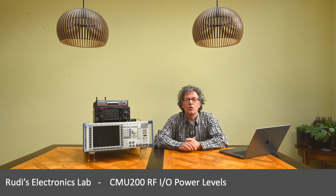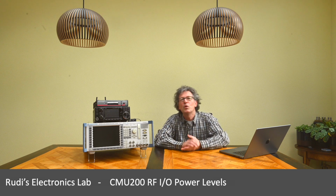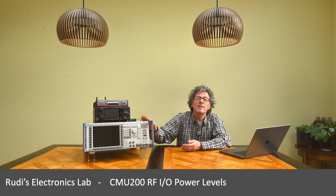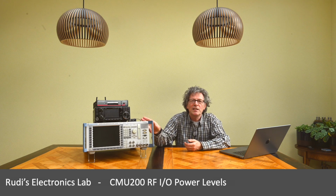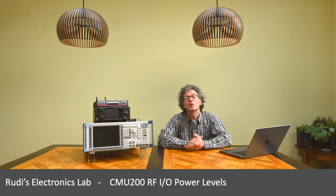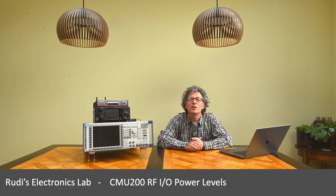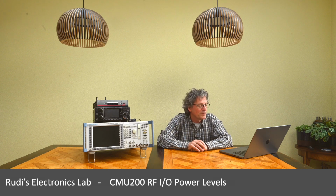You would normally have at minimum 2 different channels installed there, 2 different transmitters, with one of them having this BCCH channel, and the other one could be full of traffic slots. So you can mimic this basically in this way. And also in other standards, it might be important to have another type of carrier. There might be a pilot signal or whatever going on. So I think you really have to see the availability and the features of this in the light of what it was originally designed for. But we can use it for generic purposes, and I've used it for a couple of things. I hope this gives you some idea why we have this kind of unusual configuration of such a weak signal generator here.